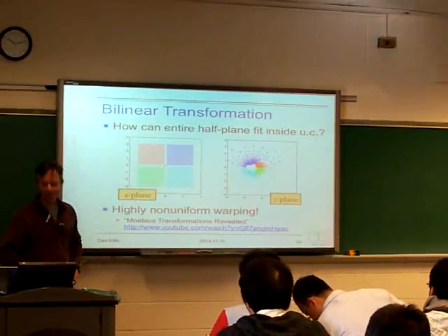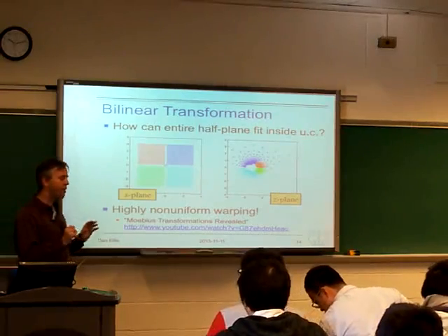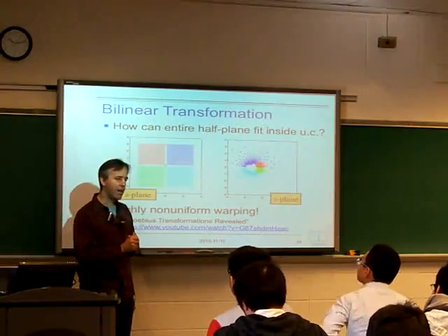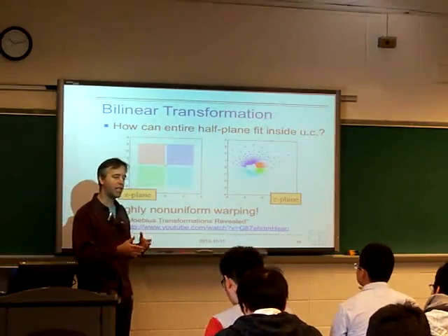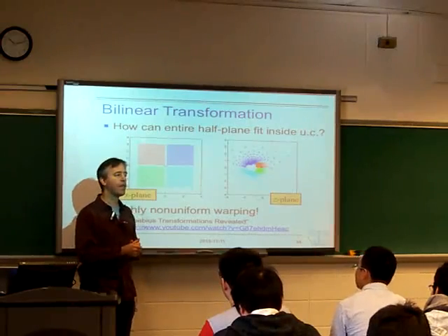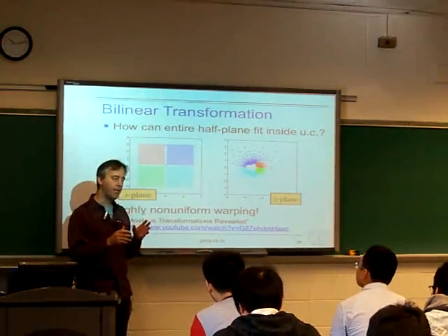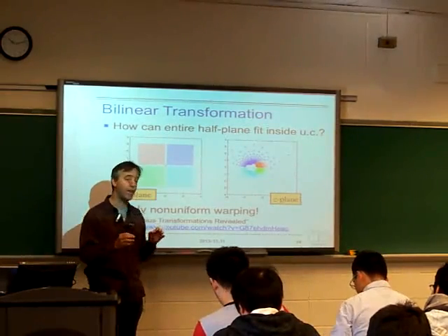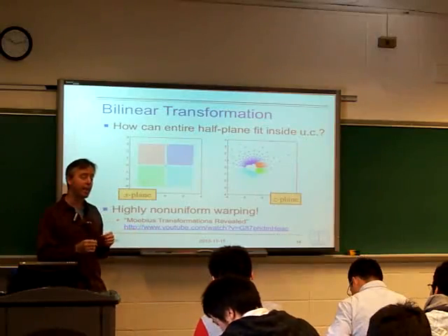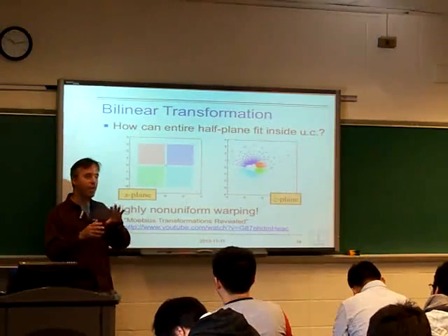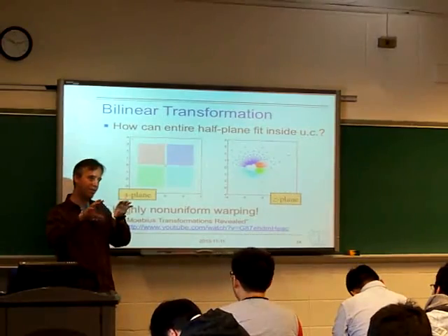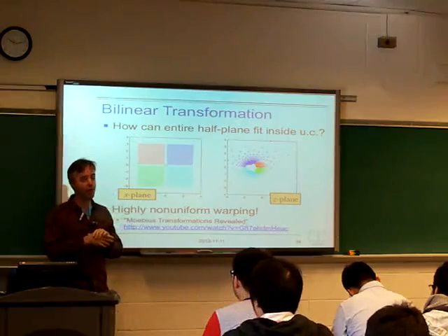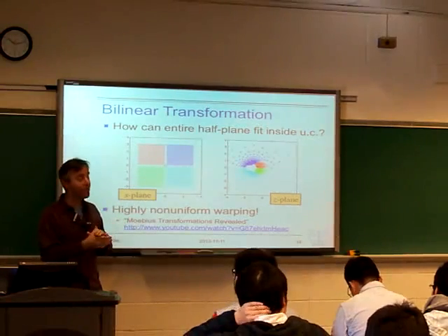So let's get started. We went through this process of learning how to design analog domain filters, the Butterworth, Chebyshev, elliptical filters. And we had these techniques, these polynomials that have this nice property of having equal-sized ripples in their magnitude responses, because when you push down a ripple somewhere, it's going to pop up somewhere else, sort of intuitively.